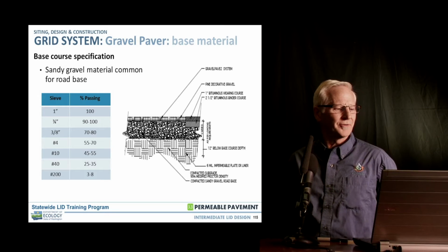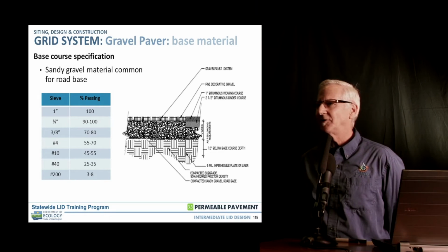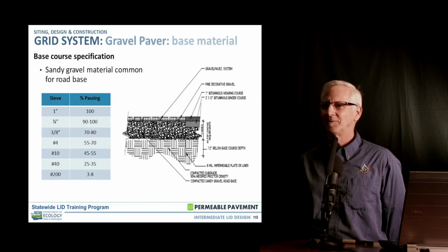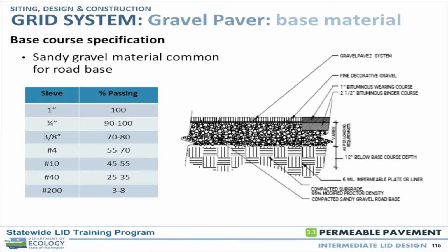Look at the drawing. If you're thinking about using a system like this, and you go on site and you see this drawing and you look through it, any red flags, anything interesting that pops out? Calling out for 95% compaction on your subgrade makes you wonder, what do you do? I get on the horn with the vendor and say, well, is that right? Well, in fact, Invisible Structures doesn't really call that out anymore. And you can use these systems on a subgrade that's not at that compaction effort.